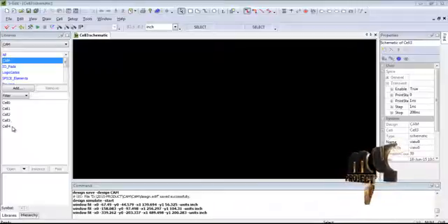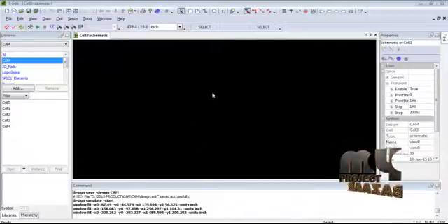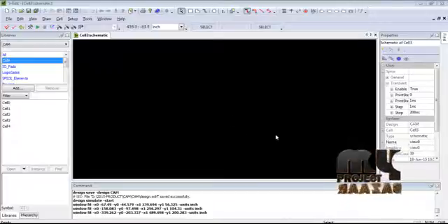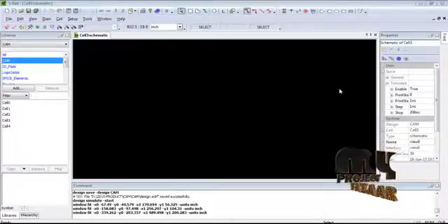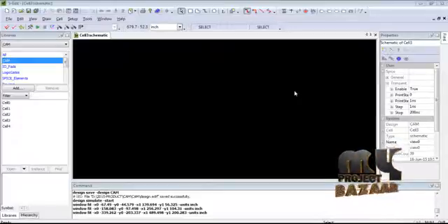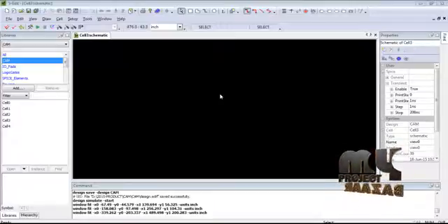Then the final design. This final design is given the input data for the data bit register and creates the 4x4 array cell design. Then the data bit register is compared with each and every row, using the match line sense amplification process. This amplification process shows which line is equal for the overall CAM cell array. Then to get the content, the main focus is the match line detection process. This is our overall design for CAM cell memory storage for efficient content retrieval.